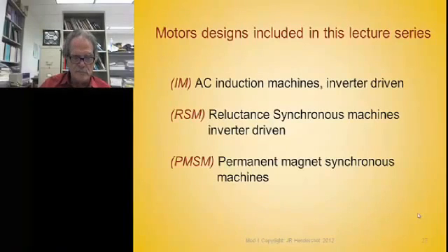And finally, we're going to use the same stator and put a permanent magnet rotor in there to run it as a permanent magnet synchronous machine and see what we have to do to optimize the rotor to get the best performance. And best performance means the highest torque density at the lowest input power. That's what best performance means. Efficiency, power factor, things of that sort.